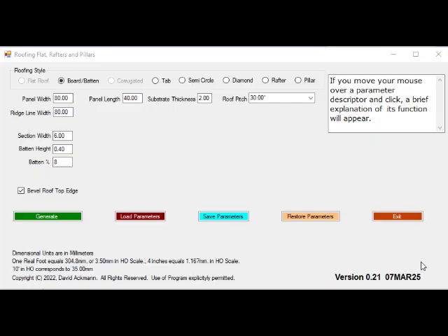It's shortened to the value specified by the ridgeline width, which itself must be less than the panel width value. And the difference between these two fields is the amount of the indent at the ends. So, for a hip roof, just specify all the other general parameters as needed for a standard roof, and then specify the length of the ridge line width.